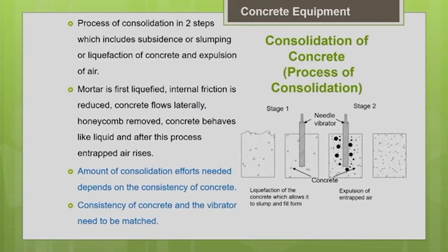Your concrete will slump or subside, and it will completely fill the formwork. This will result in the rising of your entrapped air to the surface. So this is how the consolidation process happens. The process occurs in two steps, which include subsidence, slumping or liquefaction of concrete, and then expulsion of the air. The mortar will be liquefied first.